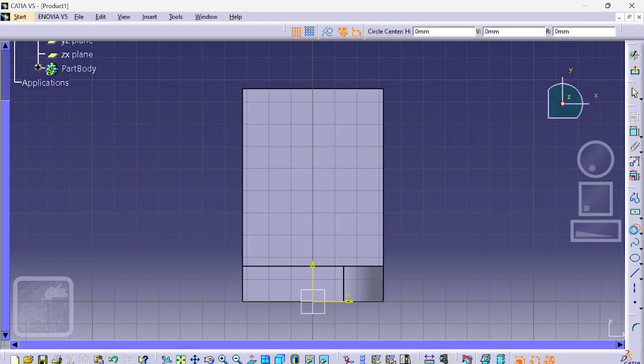So randomly first use the circle command. Go over here and create one circle. Don't make the circle from this center. Okay, just offset you have to take, and you have to create one circle. Create, done. Okay. Now give the dimension to this circle. Click over this command and blue box command and select your circle.